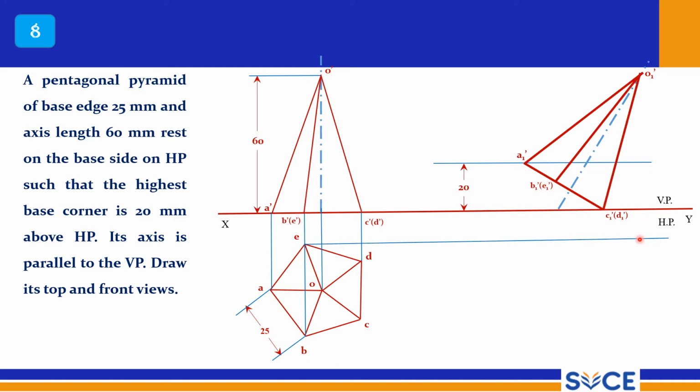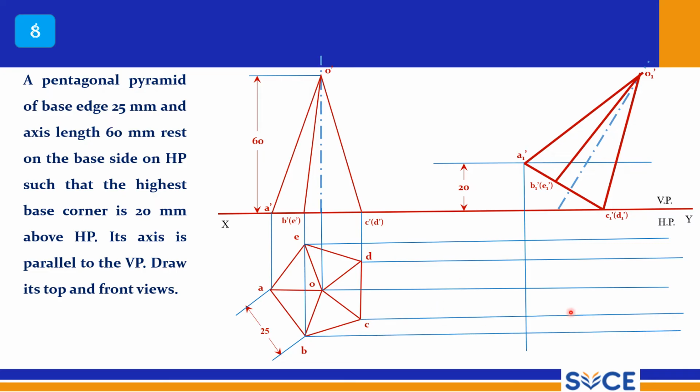So this is how you should draw. There is no angle given. Instead, the A position is given, right? So to draw that A position, draw a 20 mm line above the XY reference line. You mark a point somewhere, anywhere. From there, measure this distance and cut an arc, right? So now complete the line. So that becomes your base. From that base, you reproduce this view. So this view is reproduced here. Now the remaining exercise will be as usual.